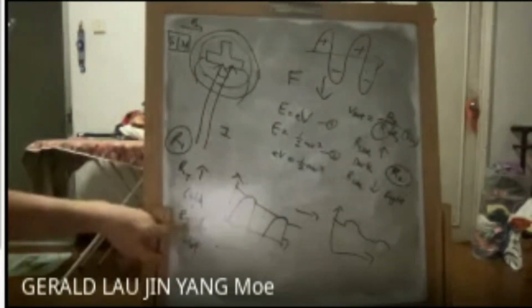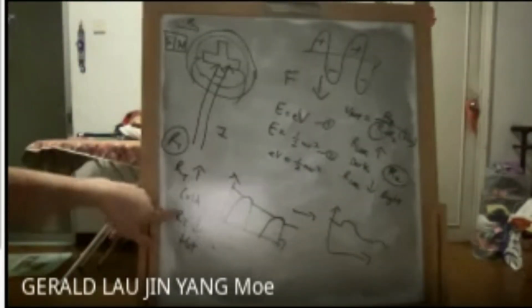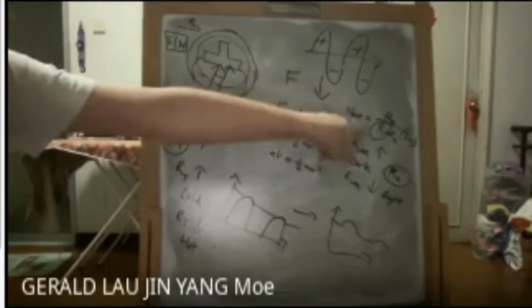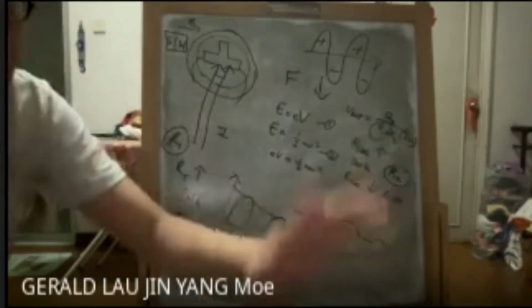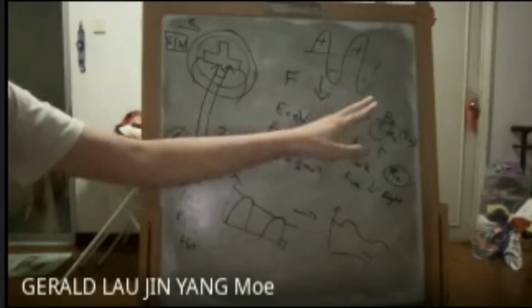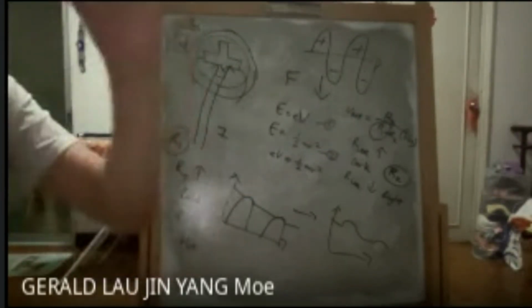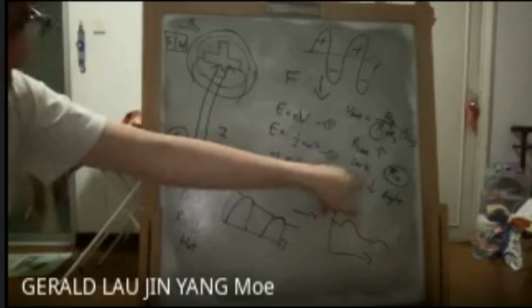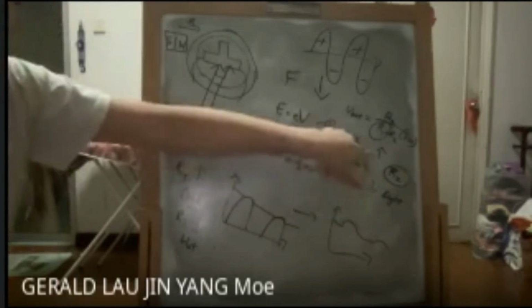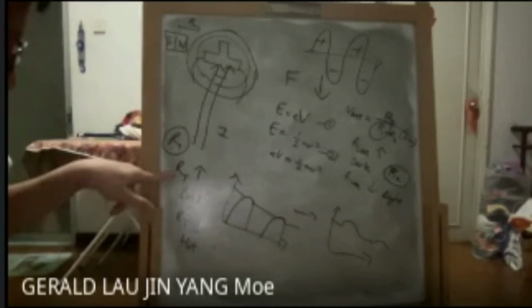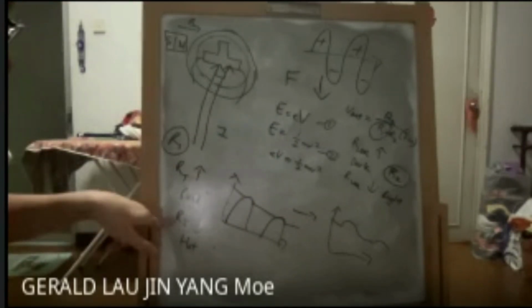So, in hot condition, resistance of the thermistor is low, and the voltage will rise because it is inversely proportional. Confusing, right? Very confusing, right? Okay, I'll give you time to understand. The most important thing is you have to know the condition: if it's dark, what is the resistance; if bright, what is the condition; cold, what is the resistance; hot, what is the resistance.